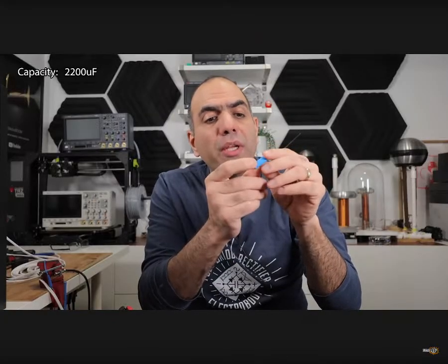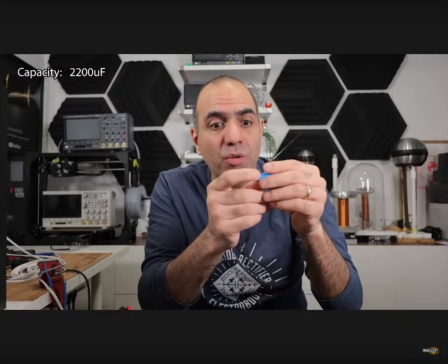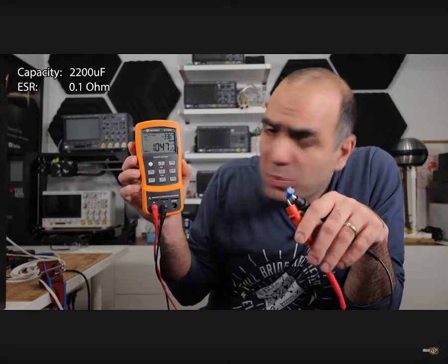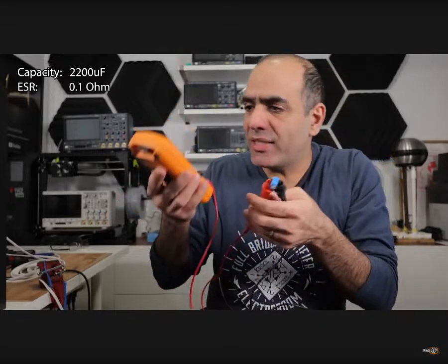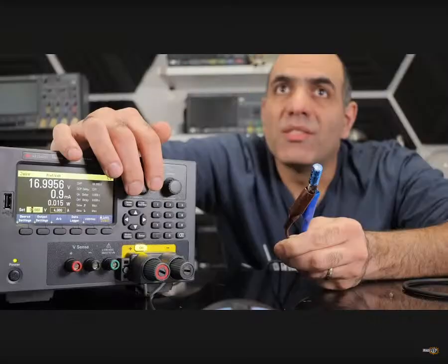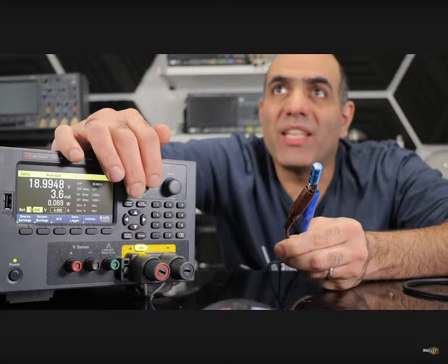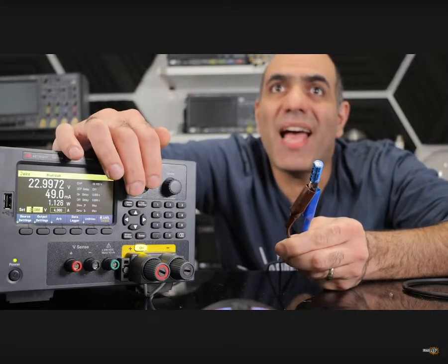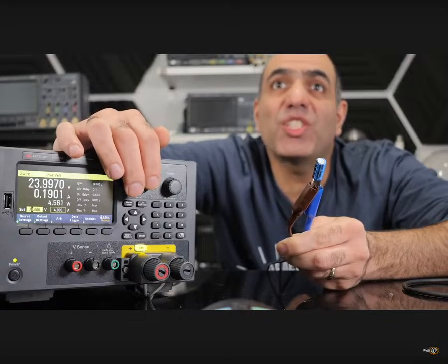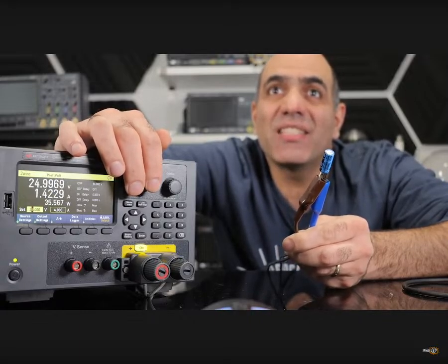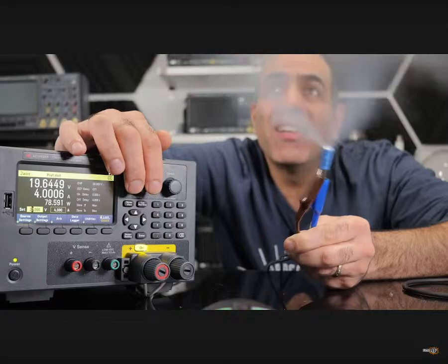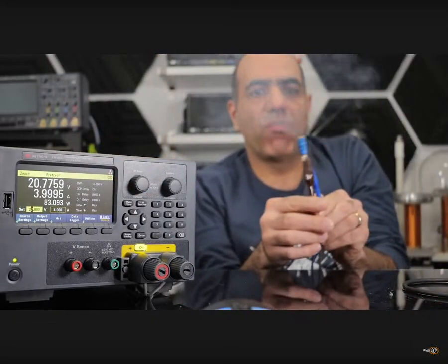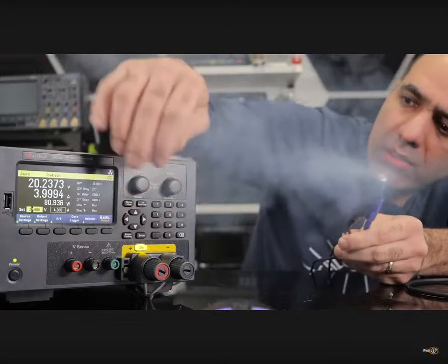This is a healthy 2200 microfarad capacitor with an ESR of around 0.1 ohms, and the parallel resistance is over 6 mega ohms. So when I overload the capacitor and it bulges, those tiny grooves on the top break open, allowing the release of the pressurized gases, and this will save the... Woohoo. Well, stop it.